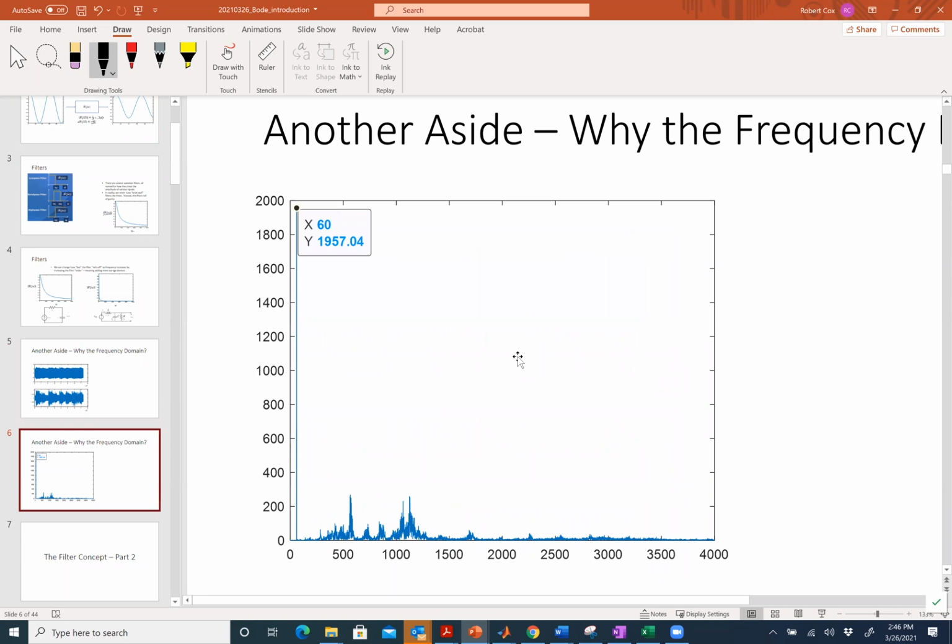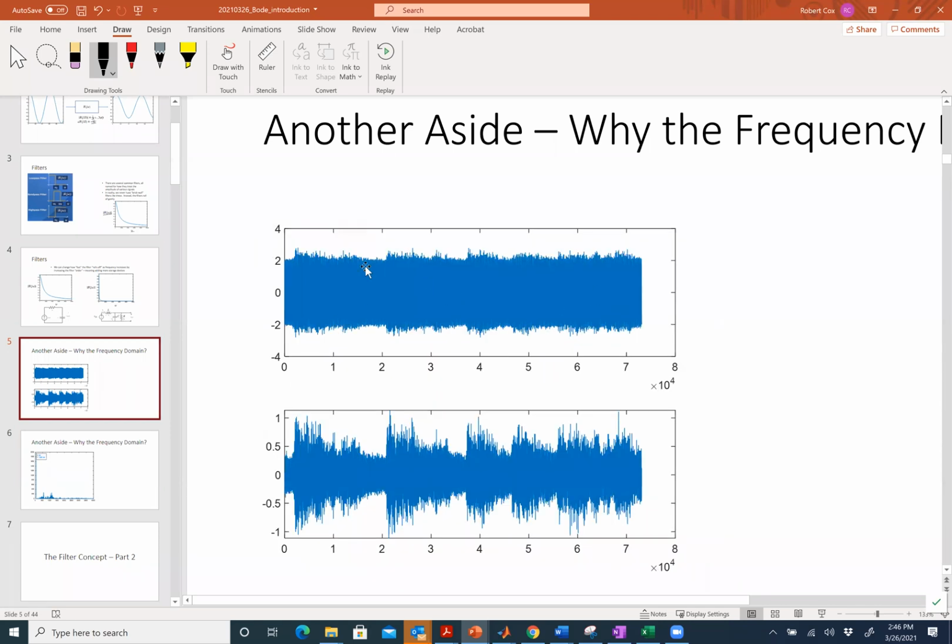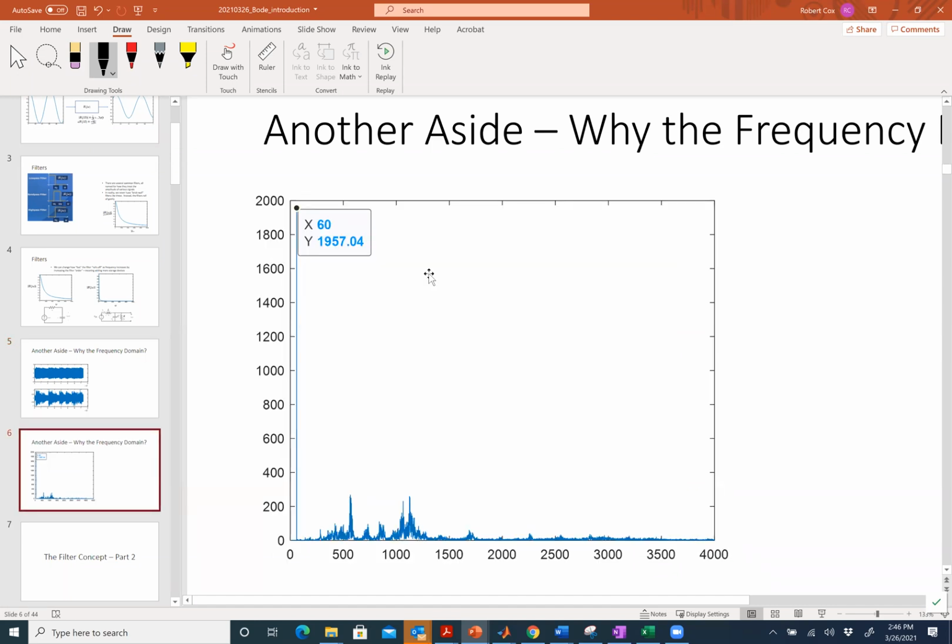So what this does is it looks at these signals, right? It looks at these guys. Oh boy. I guess those plots are big. All right. It looks at these signals and it says, what are the frequencies in there and what's the phasor at each of those frequencies? And so what I've got here on this slide is that's the noise right there. I got a noise at 60 hertz that's really big.